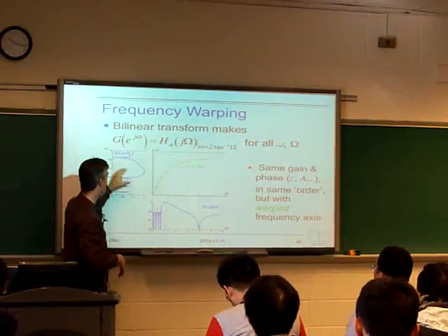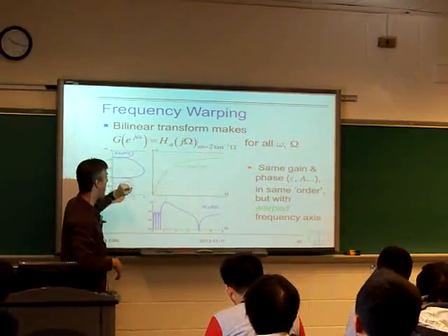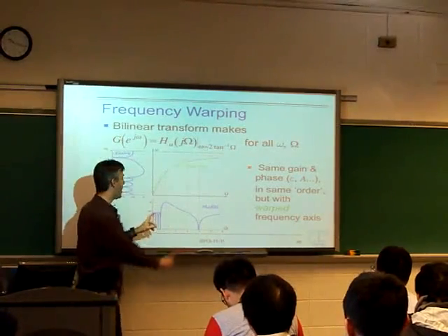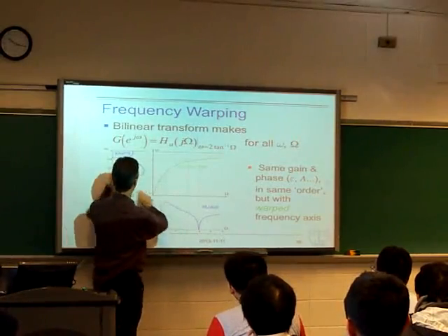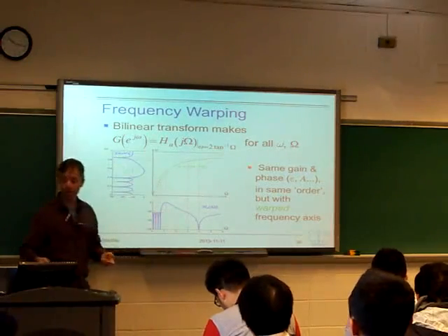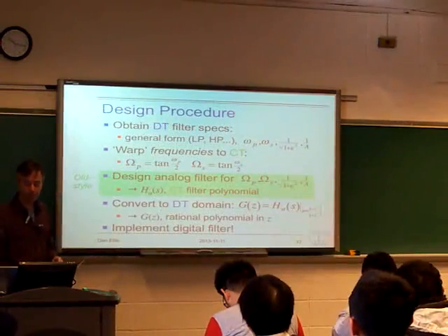But basically now we can build a discrete time bandpass filter by designing a continuous time bandpass filter and then just making sure that the frequencies that we need in the discrete time are placed in the right place in continuous time, which is this idea of pre-warping.